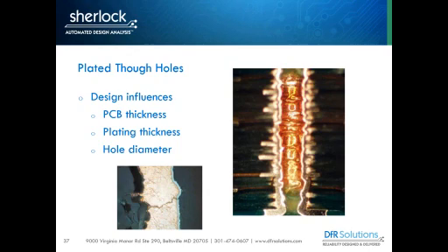I would say aspect ratio is one of the key drivers. The smaller the diameter of the hole, the less fatigue resistant it's going to be. So, go to the larger holes. It's easier to plate. It's easier for the printed board shops to drill, and to make sure they do get the chemistry in there to plate it right. But if you have the choice of going with a larger hole, do it, as long as you can fit it into your design.